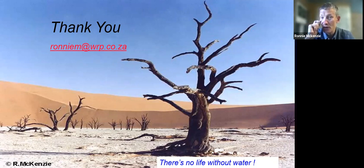I do understand that if your valve is clattering against a seat, it can put shock waves into your system, in which case your valve would probably be oversized or undersized, and it's causing that. I would actually say a PRV is quite a useful thing for reducing water hammer in a network.